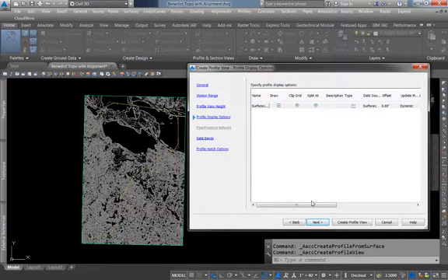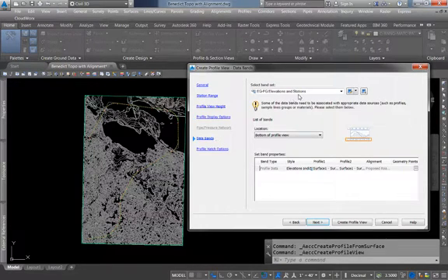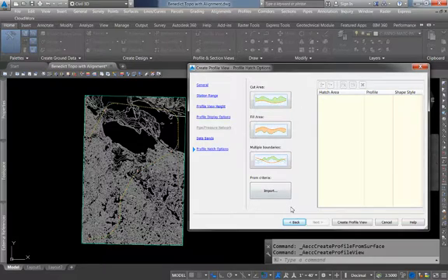I'll leave the options alone. We are going to draw it. We could do all kinds of editing here for the display options. I'll leave this all alone for now and just click next. For data bands, I will change our data bands to no bands for now, but if you did want to see some additional information at the bottom of our grid views, we would select a data band, or if you wanted to move it to the top. But again, no bands for this video. And then I will click next. Also, no hatch will I be adding to our table for now. I'll just leave it alone at the default, and we'll see what we get when I click Create Profile View.